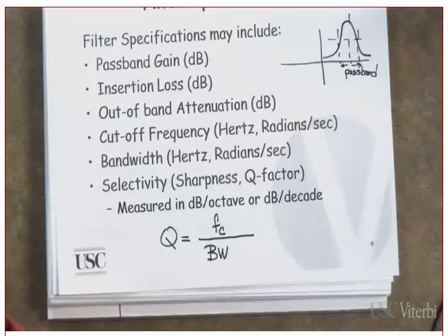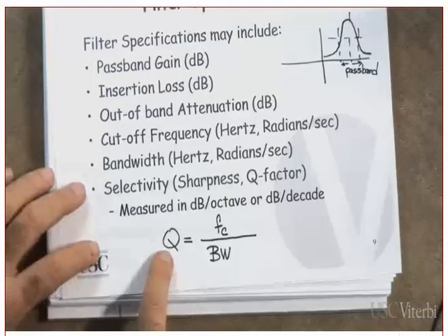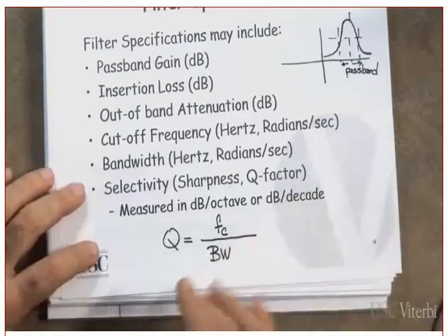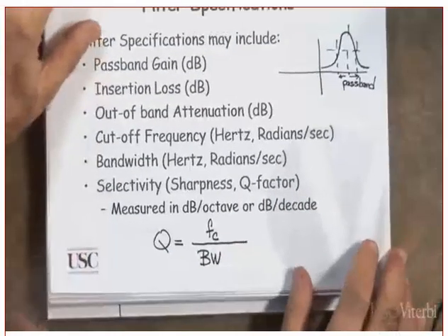We will see that at the beginning, we will select the band rather than select the channel. We will leave selecting the channel to the IF, or even all the way to the baseband. At the beginning, we select the band so that the Q is relatively small. Clear? Okay, we'll get to that shortly.